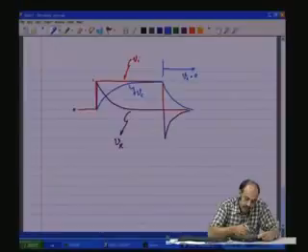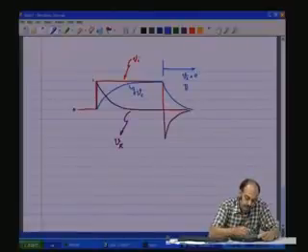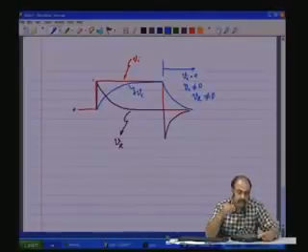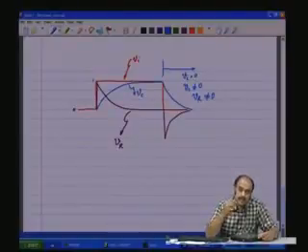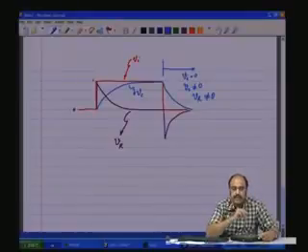So, when Vi is equal to 0, in both the cases, the VR and the Vc voltages are non-zero. Vc is not equal to 0, Vr is not equal to 0. What does this mean? This means that the input voltage is 0, output is non-zero, therefore, the gain is infinite. So, this implies the existence of a pole.